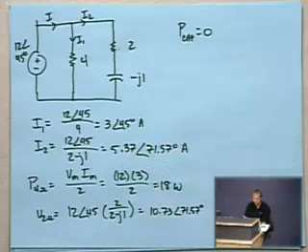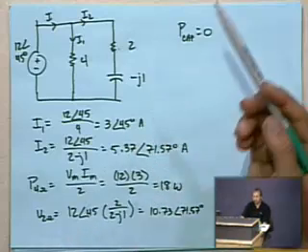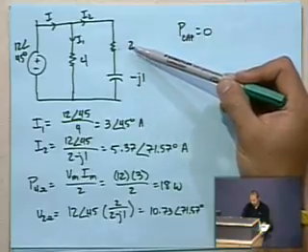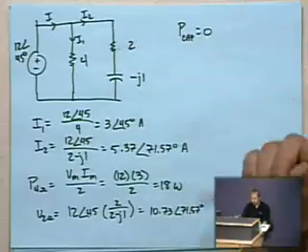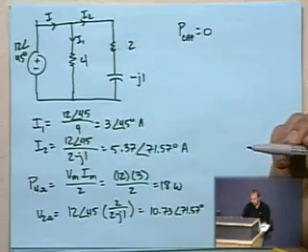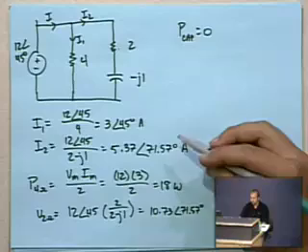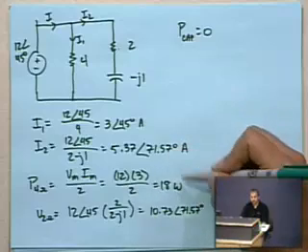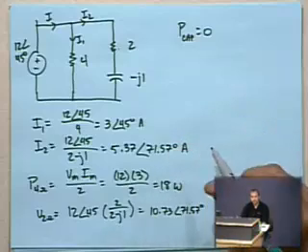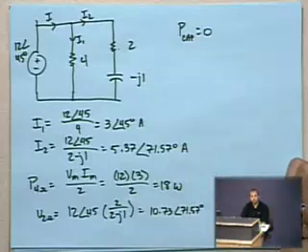So we did a voltage divider. Obviously, if you want to know the magnitude of the voltage, you could also multiply the current times 2. You should get the same thing both ways. And what made me feel good was seeing 71.57 as the phase angle in both places. The phase angle for the resistor should be the same, right?